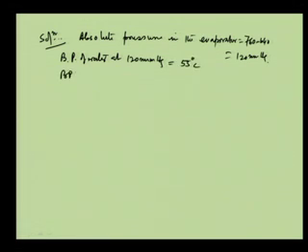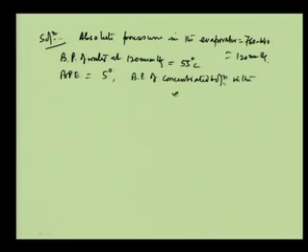The boiling point elevation is 5 degree centigrade, so the boiling point of the concentrated solution in the evaporator is 55 plus 5 equal to 60 degree centigrade, fine.